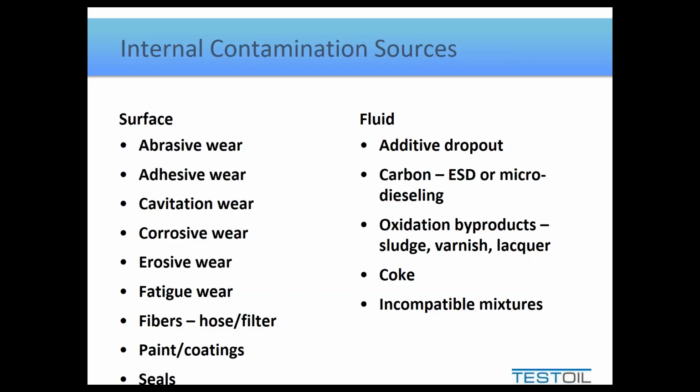And last but not least, when it comes to fluids and contaminants, we simply call it incompatible mixtures. It could just be two different oils that don't play well together. It could be oil and process fluid. It doesn't matter, but in some cases, we have them appearing as a contaminant that displaces the lubricant layer. Other times they may react with the lubricant and produce other things like gels or otherwise sludges that take on anything from the consistency of Vaseline to peanut butter, in that range, where it really starts to stick to things. It can plug up filters, plug up suction intakes, cause all kinds of problems. But these are all forms of contamination that occur internally due to sometimes normal mechanisms, but oftentimes accelerated by something abnormal happening within the system.